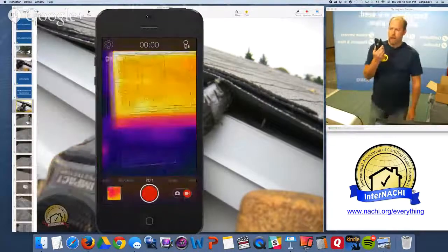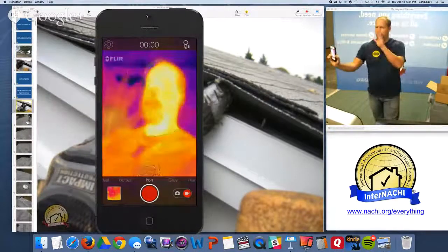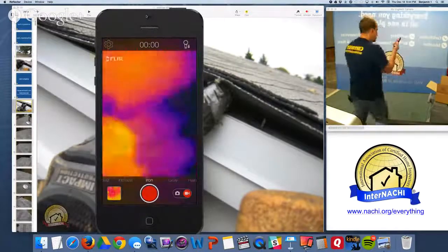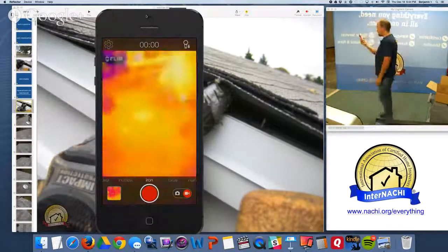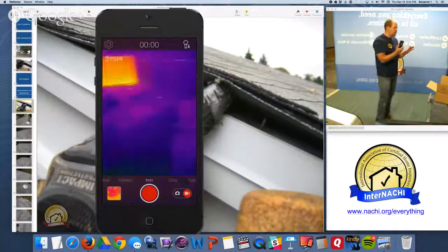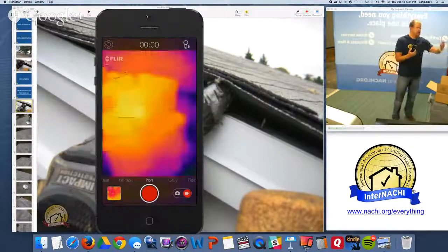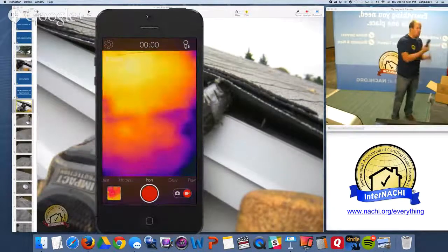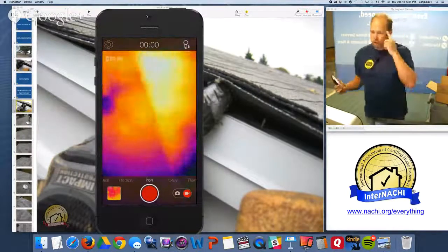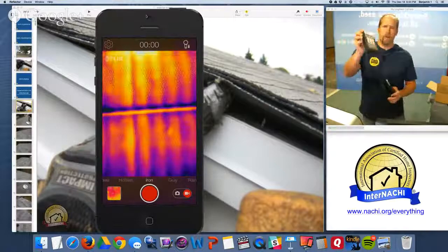when I use my FLIR iPhone infrared camera, hello. So I use this to look for anomalies around, just move it around the room, looking up, looking down. I'm not really quantifying anything. I'm not measuring anything. I'm just looking for anomalies, something different on the surface that shows some kind of different temperature. Moisture is typically an indication of, it'll look cool, but it could fool you if you're not properly trained. So you want to follow up with a moisture meter.